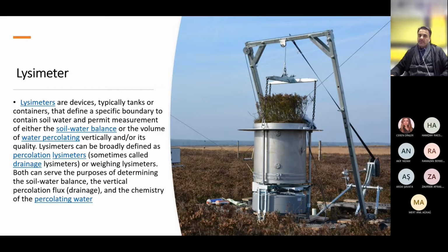Okay, there are also some other instruments that we can use to calculate the evapotranspiration directly. So far, we used pan evaporation, then adjusted it with respect to the crop type and crop season. But is it possible to measure transpiration directly? The answer is yes. For this aim, we use a lysimeter.